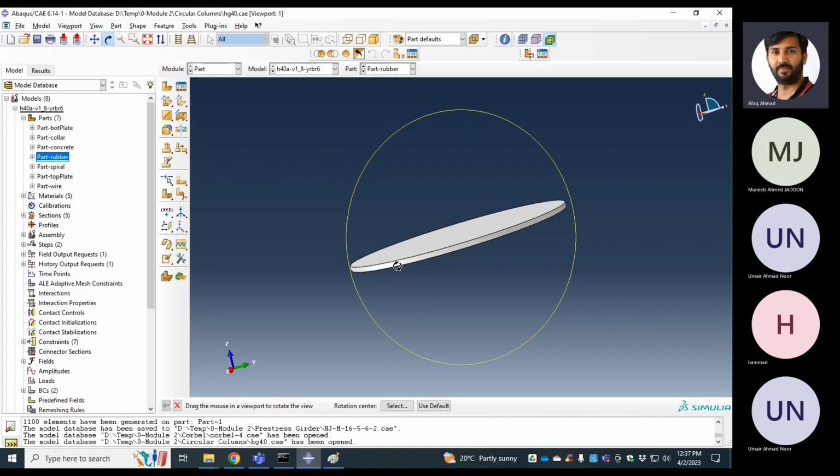So again, you are providing a smooth surface at the top face, so that when you apply the load, it is applied uniformly. If you have different strata or variable contours at the top of the concrete cylinder or the column surface, then the load is not going to be applied uniformly. So just to provide a smooth surface, in this experiment the investigator applied the rubber pad on the top of the cylinder. This rubber pad is not carrying any stresses. The only purpose of the rubber pad is to provide a smooth surface and transfer all the load on the concrete member at the same time.